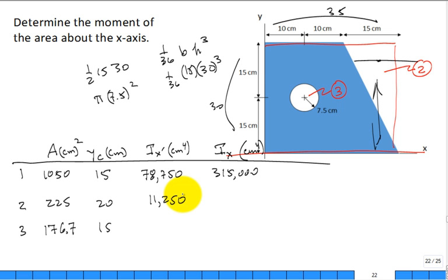No negative sign yet. All right. How about for the centroid of the hole? That's easy. What is the moment of inertia about the centroidal axis for a disk? Well, that's given over here, it's 1/4 pi r to the fourth power. I'm not going to repeat it, but it's there. And so you put in and you pick out 2,485.